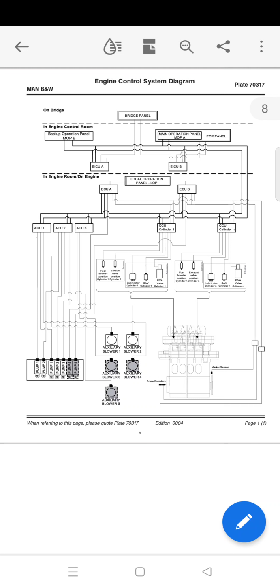Now, what are the CCUs? In appropriate time for the next firing, the CCU ensures that it has received new valid data, whereafter the injection profile start angle is set up using the tacho function. On the correct start angle, the injection is initiated and is controlled according to the fuel amount command and the injection profile command. When the injection is completed, the exhaust open and close angles are set up using the tacho function, and the exhaust valve control signal is then activated on the appropriate crank angles. The cylinder lubricator is activated according to the feed rate amount received from the ECU.